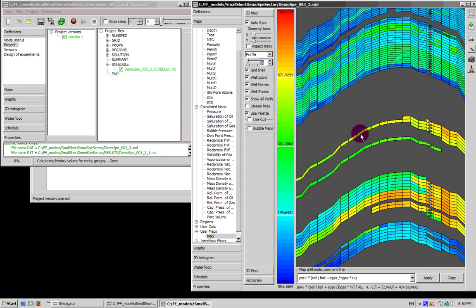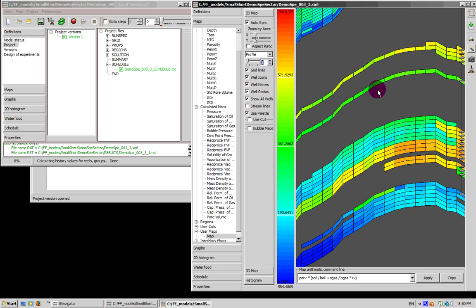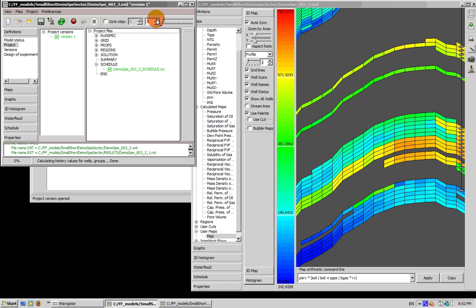Let's now construct the horizontal well trajectories. First, let's choose the time step at which we'd like to introduce our horizontal well. Let's do it from time step number 10. Alright. Next, we choose profile number 1 and let's create 3 different trajectories in each of the profiles. So at the end we get 21 different versions of the well trajectories.